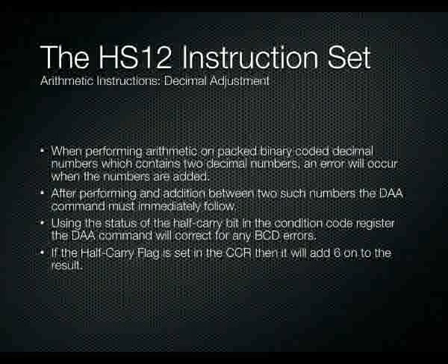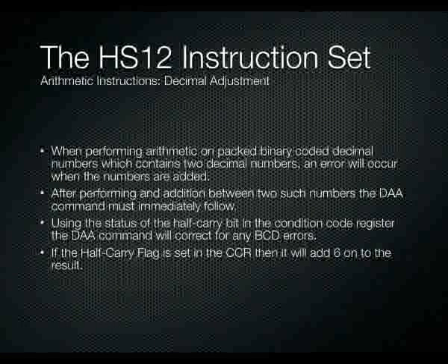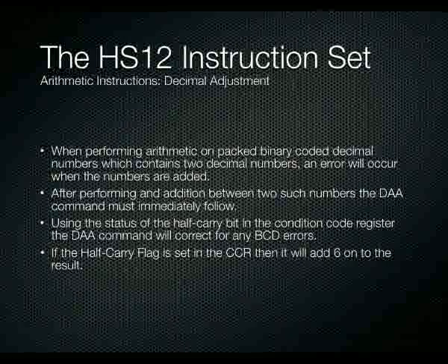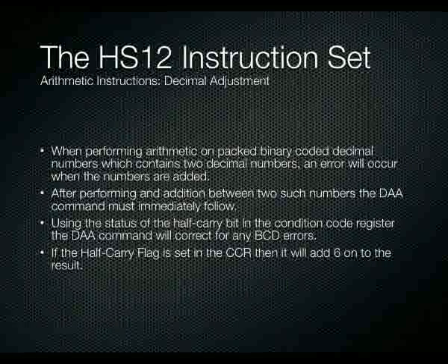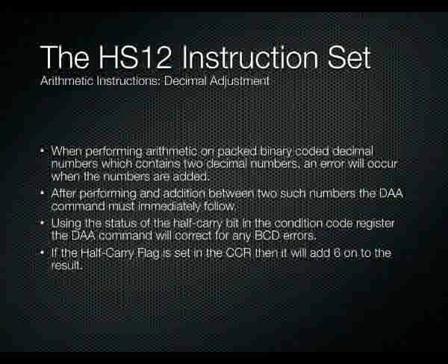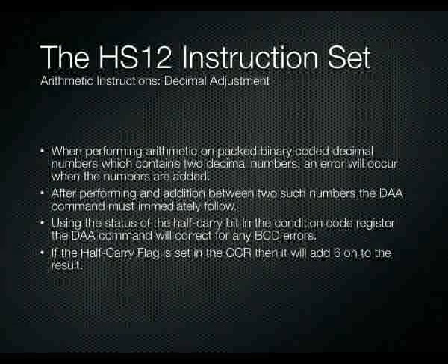But one of the beauties of this processor is that when you do this addition and you get a number greater than 10, the H flag is actually set. So the H, or half carry flag, is set to say that a number greater than 10 has resulted in those lower 4 bits. Therefore, if you run the command called DAA, which is the decimal adjust command, it will add 6 to that number to force it to become a correctly encoded binary coded decimal. So there is a command called DAA that you can run to correct for any binary coded decimal addition that you may have done.